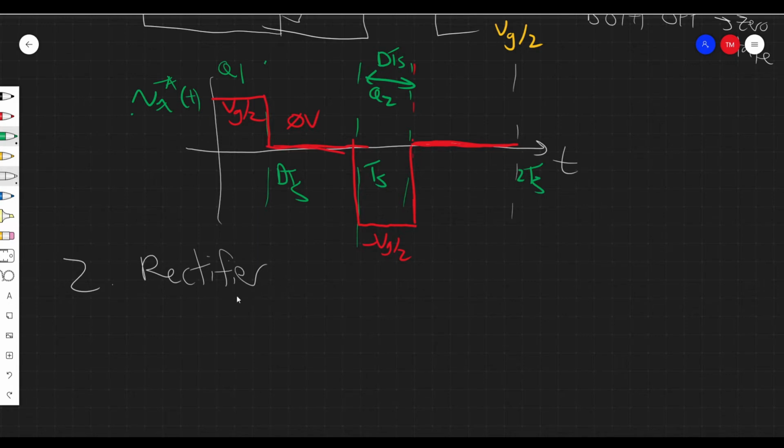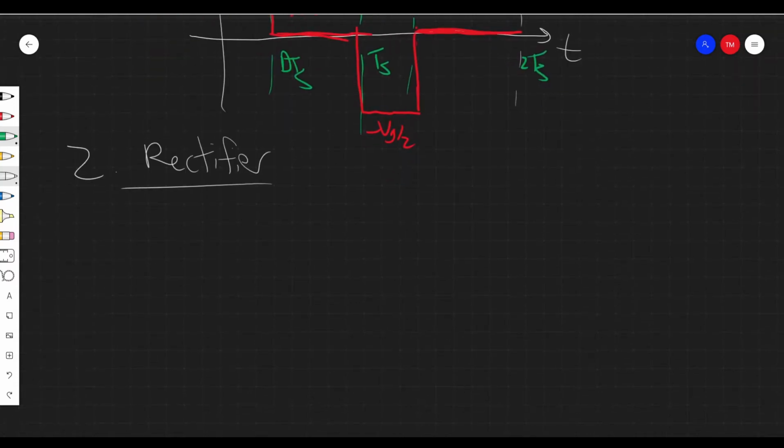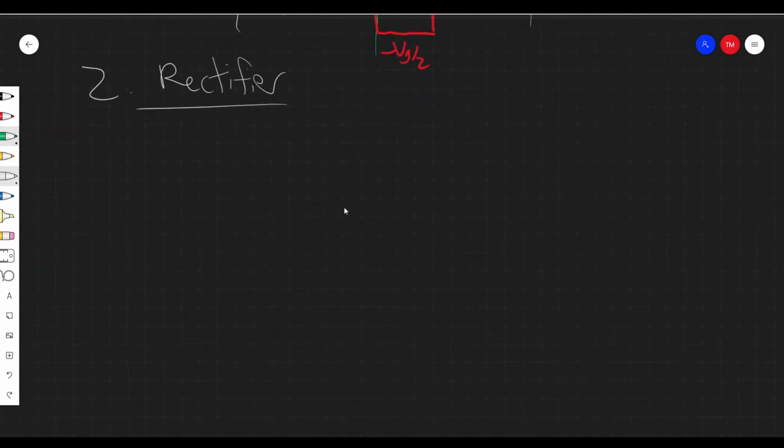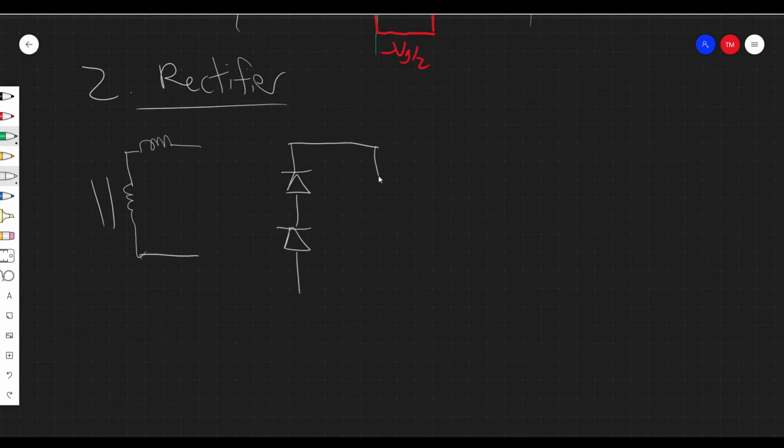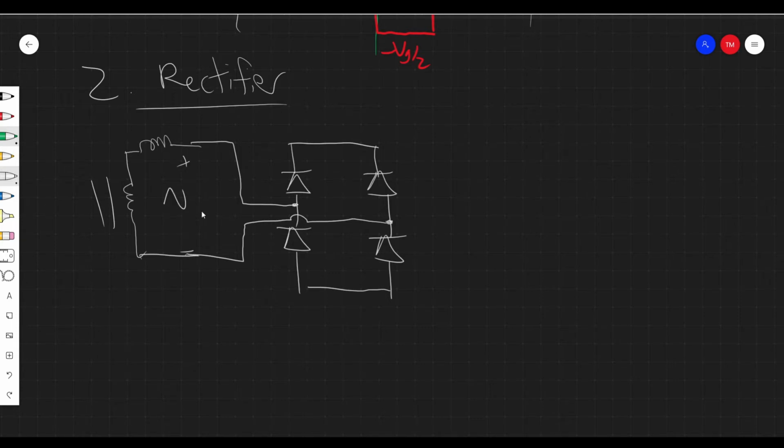And again, there are a few options for this, right? So one rectifier option, again, we can imagine here for the rectifier. So we have the output of the secondary side of the transformer, right? You can imagine the secondary side of the transformer. One thing we can do is simply have a full bridge rectifier, right? An uncontrolled rectifier, basically. So 4 diodes, right? So we connect one terminal here, and we connect another terminal to the other side, right? And if we consider this voltage, I'll call it V secondary,